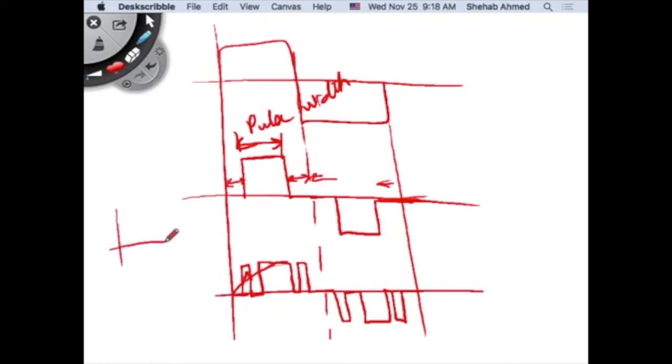So it seems it's closer to a sine wave, which rises slowly to a higher value. So here it has a small average value, this area would have a higher average value, then a small average value, then 0, right? So you're closer to a sine wave, right? So people used to program this. They call this programmed pulse width modulation.